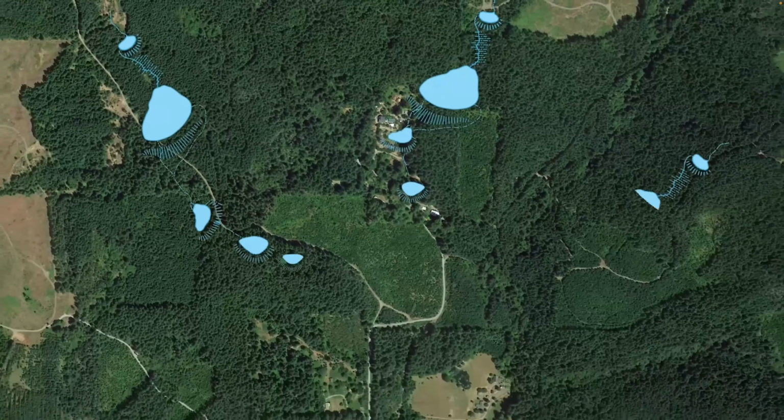If you don't have enough clay to build up a key, there is a second type of dam that can be built, and this is called a diaphragm dam. So this would be a situation where you essentially continue that clay blanket that's on the bottom of the cutoff excavation, and you work it all the way up the side of your dam. So you have an interior liner of clay that serves the purpose of preventing excessive water movement, at least through the dam.